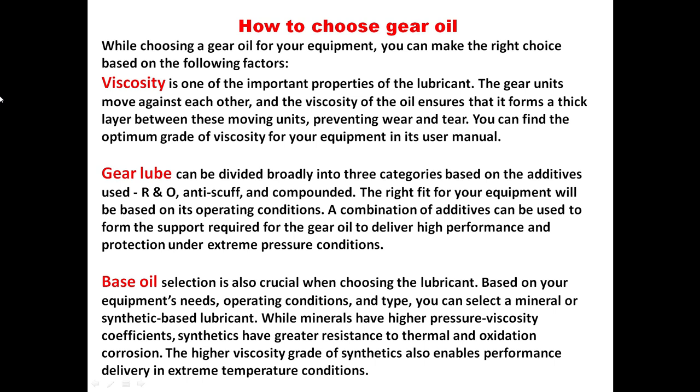Gear oil can be divided broadly into three categories based on use: R&O, EP, and compound. The right fit for your equipment will be based on its operating conditions. A combination of additives can be used to form the support required for gear oil to deliver high performance and protection under extreme pressure conditions.